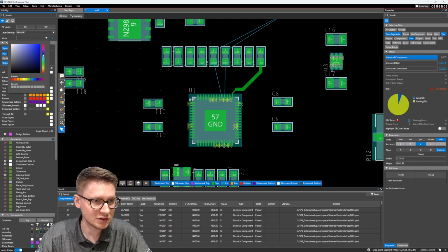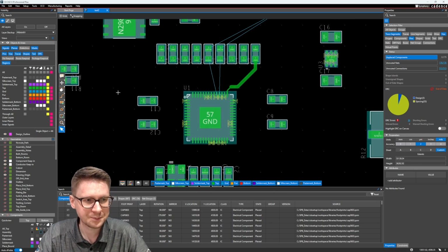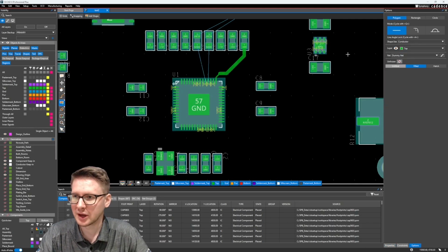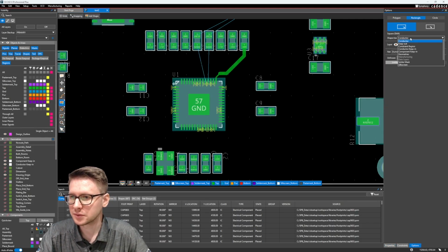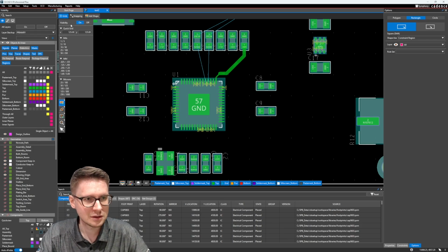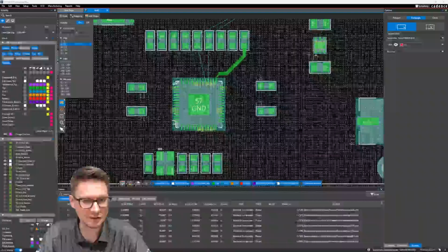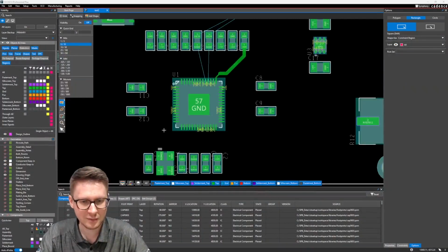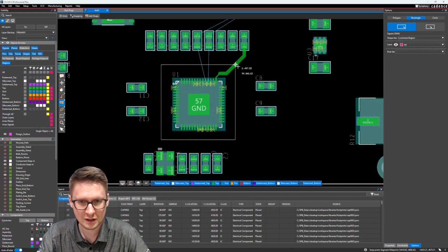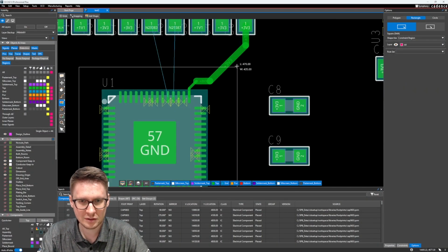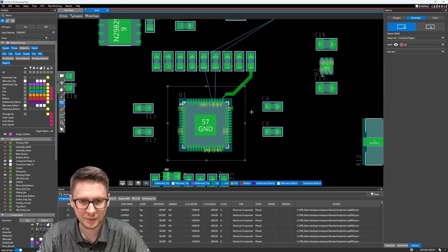And let's just set it to a uniform color really quick. So we'll use that kind of pinkish reddish color that was set before. Then we're going to go into our shape command. We'll select a rectangle, and then we want to set the shape use to constraint region and the layer to be on all layers. And then using our grid, let's set it to a 510 grid. Ooh, and we can turn that off. We just need to draw a square right around this microcontroller.